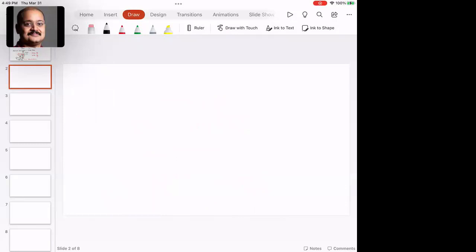So I'm going to give you something like speed of pinion divided by the speed of gear. Please note, pinion is going to rotate at higher RPM than gear. So speed of the pinion divided by speed of the gear is typically equal to or greater than 1. This is called the velocity ratio